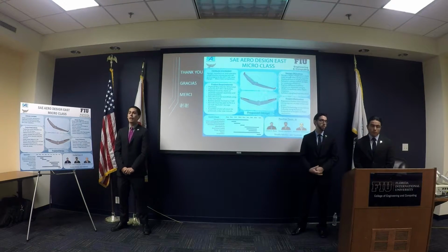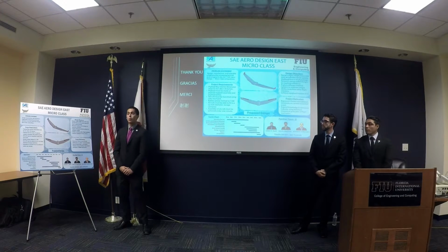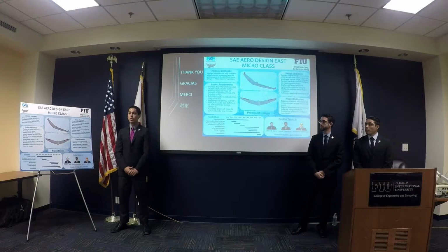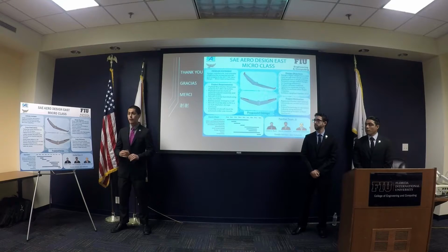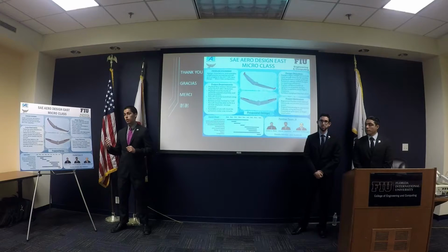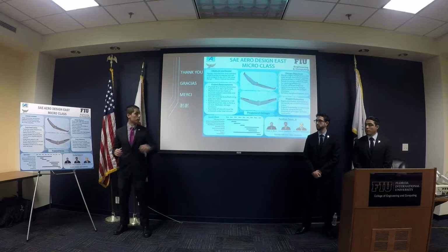And to add to what he said, we are currently using, for a quick design phase, a program called XFLR5. It does very quick CFD analysis, and we just put in our parameters, and it's parametric. So it will give us a good idea of whether the wing is stable or not at different flight conditions, at different Reynolds numbers, at different altitudes. It's all programmable. This is just to make sure we're heading in the right direction. Obviously, the sizing of a wing is very, very important. Once we have the sizing set down, we will introduce more sophisticated programs such as ANSYS and really, truly calculate it.